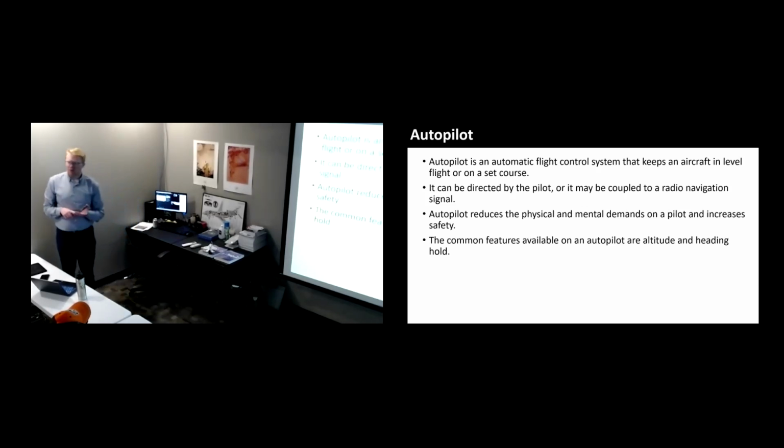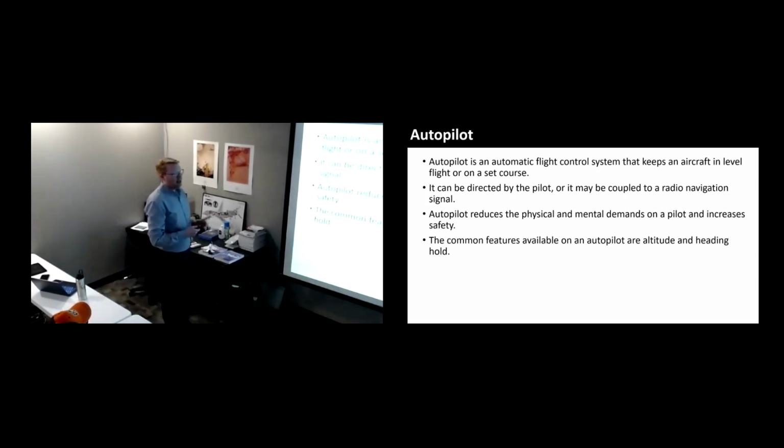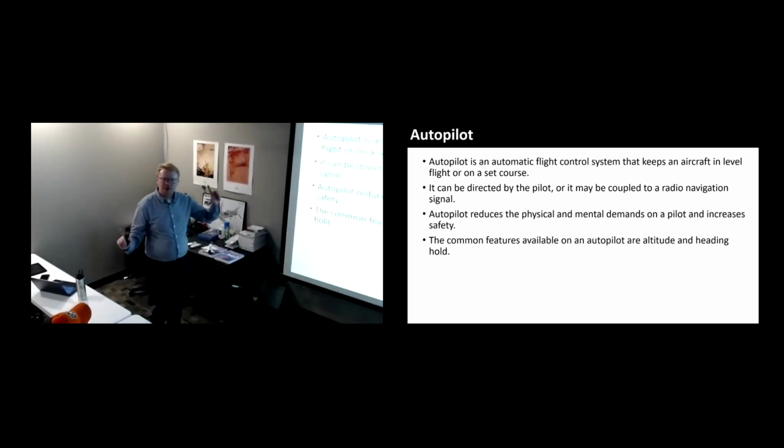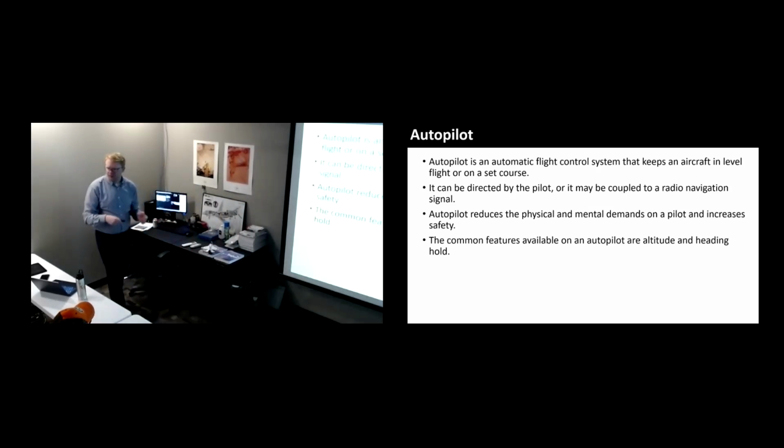Some autopilots only have roll control or pitch control or yaw control. Most small airplanes we're flying control two things. It's a two-axis autopilot, usually altitude and heading hold. So an altitude hold allows for pitch up and down. So that's adjusting elevator input, either by physically adjusting the elevator or trim setup, depending on the autopilot design. And then roll to control heading is aileron movement, that it just allows the ailerons to.